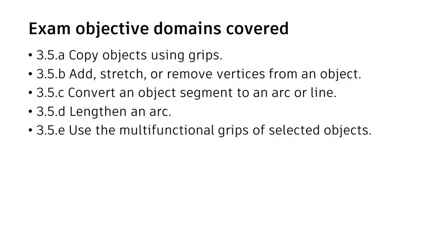Sometimes we move through our drawings so quickly we forget to hover. To use the options in multifunctional grips, hovering is essential. Depending on the object selected, different multifunctional options are available. In this lesson, we used the multifunctional options available in polylines and arcs.